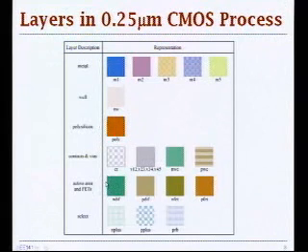And then we have active area. We have N diffusion and P diffusion for N FETs and P FETs. And also there are these two layers that you can use to automatically create a transistor: you basically overlay your poly, and the diffusion is treated as a transistor. So you can automatically put your transistor down with this N FET and P FET layers. And then you have these select layers for your contacts.